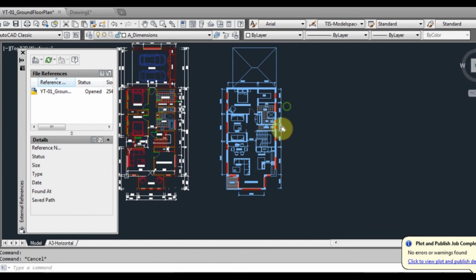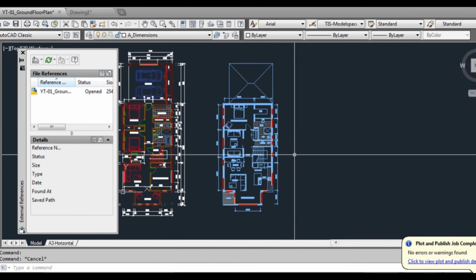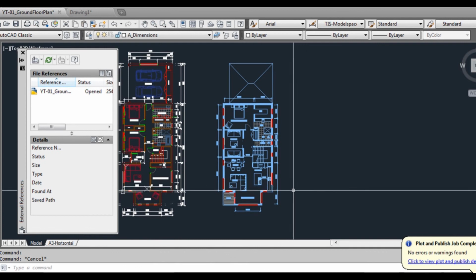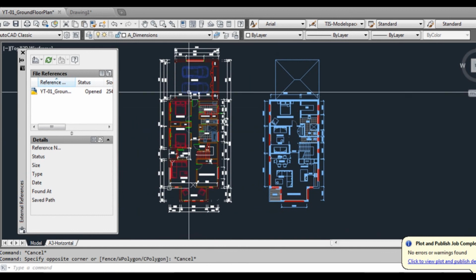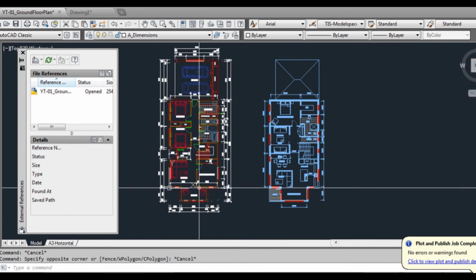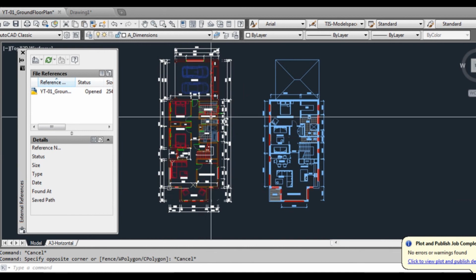But it's not always recommended. Depends on what you're doing, but it could be a bit of a problem if, for instance, we exploded that over the top of all this line work. We'd have a real mess to try and clean all that up, having to select all these lines individually to get rid of them. I mean, we could also turn off the layers.